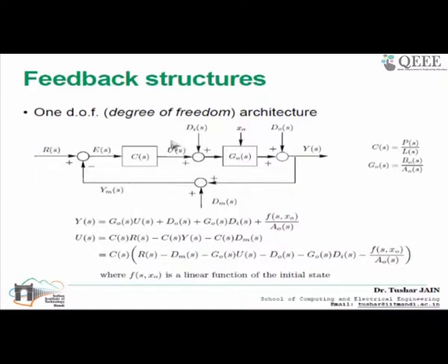If you are able to say that your U and Y are stable, then your whole closed loop system would be stable. So that's why I start writing the equation for Y and U. First visualize this equation, Y of S, which is what? Since we are considering the linear time invariant system, you can neglect one signal, just consider one signal except the other signals, and then sum them up to see the total response.